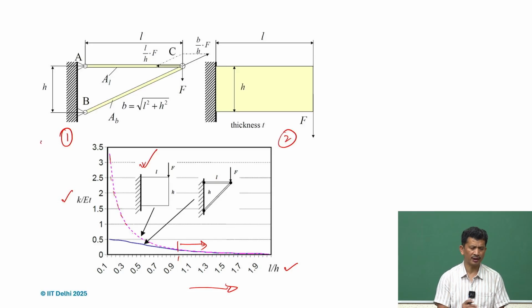What we also realize is that in the case of trusses, the kind of forces coming on the members, on the links, is again longitudinal. So, either it is in tension or compression, and that also qualifies that the weight or the stresses are evenly distributed on the links.